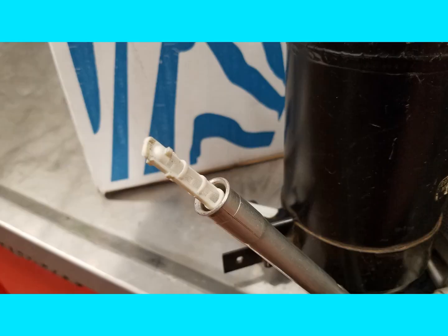This is just showing the orifice tube being installed. We'd put a little refrigerant oil on the O-ring so it would slide in there properly, and we'd push it in so it would be flush with the end of this fitting. So we would push it in to this point. That way we can grab the tabs either with a tool or grab this piece right here with a pair of needle nose pliers to pull it out.